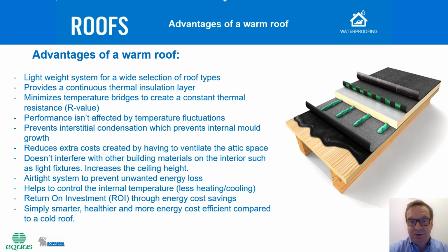Internal air and external air will now be separated. They can't meet each other anymore on the inside of the roof structure, so there is no need for an internal roof cavity that needs to be ventilated. This makes the design much easier.